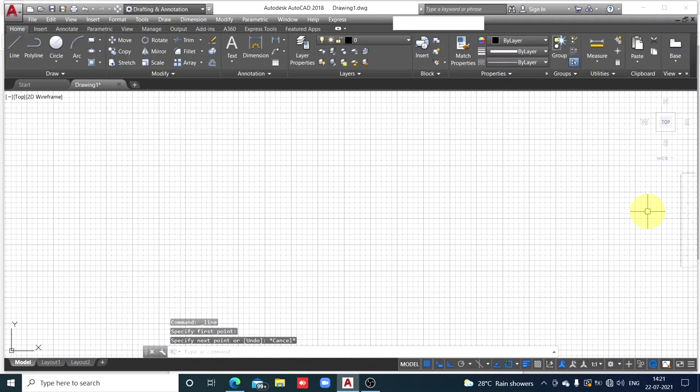Just now we check the dimensions: 60 millimeter height, length 120 millimeters, and how much width is required? 70 millimeters. So approximately, just I am adding larger two dimensions, say 120 and 70. So 190, approximately 200 millimeter by 200 millimeter space is required. So we'll set a limit for our drawing paper.